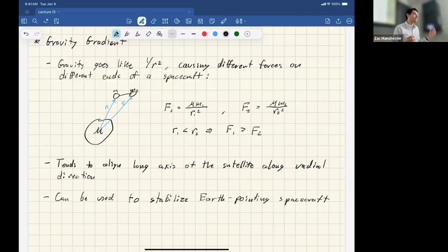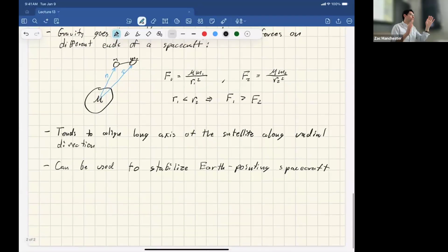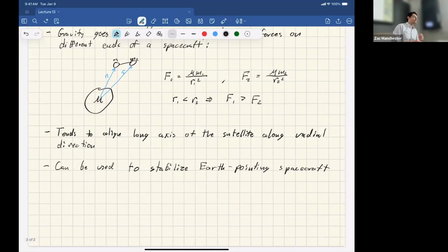Okay. Any other fun things to think about? So one thing that's worth mentioning is this effect. Even though you might model J2 and higher order gravity effects when you're doing orbit propagation, it turns out this effect is already pretty small, such that we really only worry about the spherical term when we do gravity gradient. The J2 term is so small that it doesn't matter. It's many orders of magnitude down. So generally just worry about this. Okay. Anything before we keep moving?